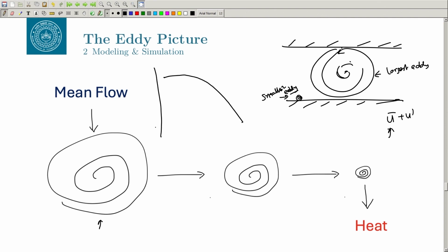Okay. If you look at the cascade picture, this is your energy cascade, E k versus k. So, k you can think of as the inverse of the eddy size. Okay. So, wave number is the inverse of the eddy size. So, if k is bigger, then the eddy is smaller, right. So, this is the smallest eddy, and this is, let us say, your largest eddy, right.